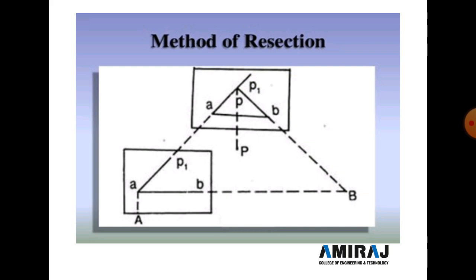Suppose these rays intersect the previous ray at point p. So this is the P station, and the actual position of the station is marked on the ground, transferred from paper to ground by the plumb bob. This is the method of resection.